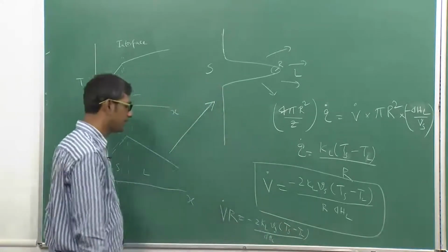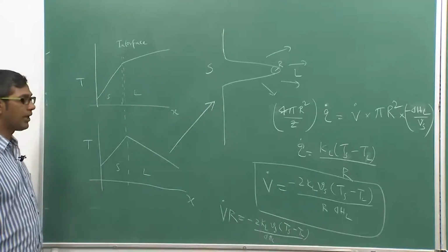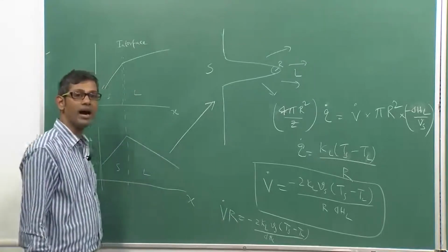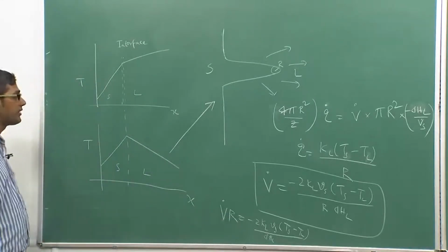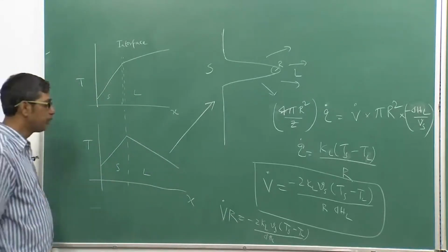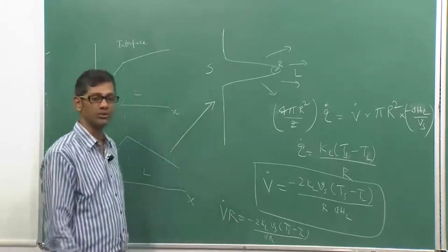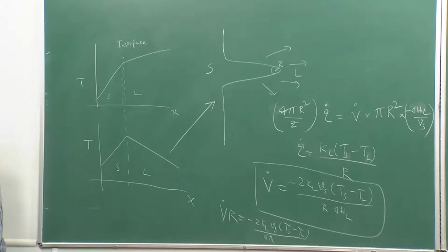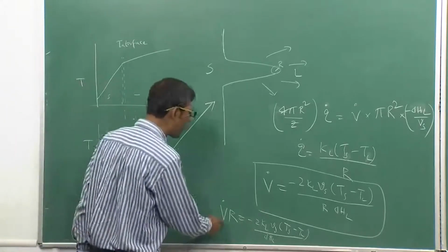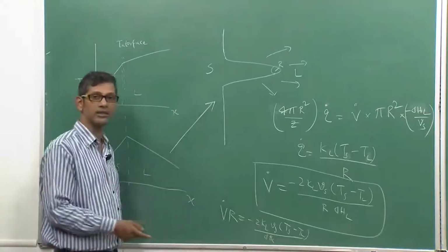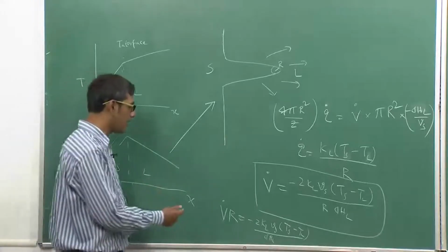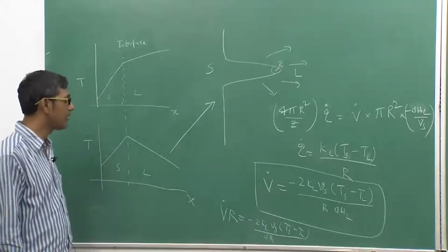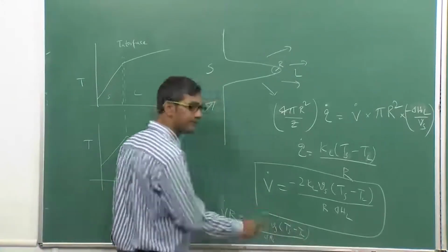So if I have any idea of measuring the undercooling, then I can calculate V multiplied by R, that is the growth rate multiplied by the tip radius. But remember, both of these are actually unknown because I do not know the tip radius a priori. I want to calculate V dot, the growth rate. So finally I get down to an equation which tells me that these two are related to each other by a function.